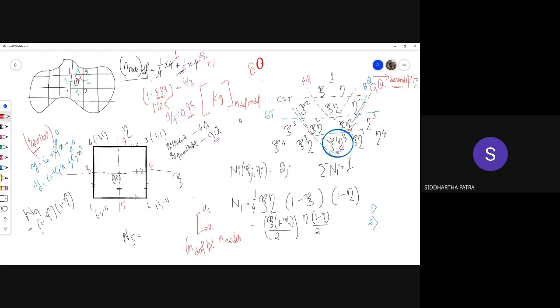I mean, you might be thinking, why does the cost of computation matter? But imagine in an industry, if you are running a finite element simulation, you probably have 1,000,000 nodes. Then for a 3D simulation, there are 3,000,000 degrees of freedom, and that probably takes over a week for a single simulation. In that week, if you increase the cost by 33%, that becomes around 9 to 10 days. Two or three more days could be extremely costly if you are running multiple such simulations.